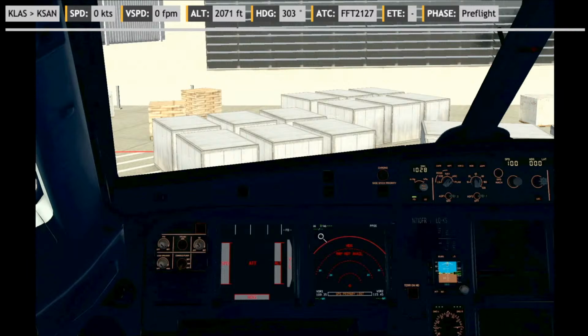And weather, that's what I was doing. Then 10 statute miles of visibility or more, clear skies, temperature 12, minus 16 is the dew point. Let's see, QNH, altimeter 30.37, and that's it. Forecast looks fine. San Diego, similar, no clouds, winds 270 at 4 knots, forecast variable at 4. And no changes in the forecast.